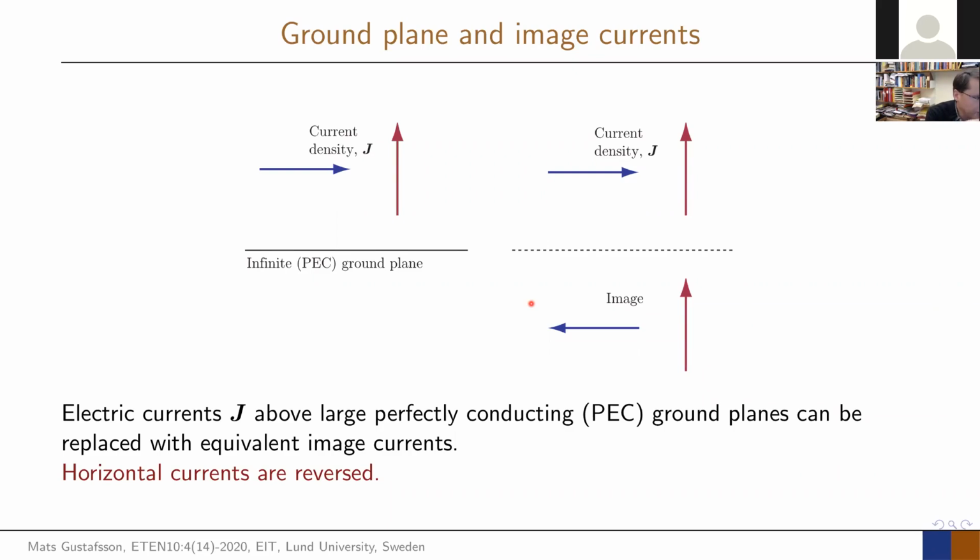So where we were just before the break is that we start looking at this monopole. And the monopole antenna is an antenna that sits above a ground plane. And a ground plane is a big conducting object. So in the ideal case, it's what says here, like an infinite PEC plane. So infinite, which means extent in this XY plane, and perfectly electric conducting. So that's of course an idealization of a real condition.